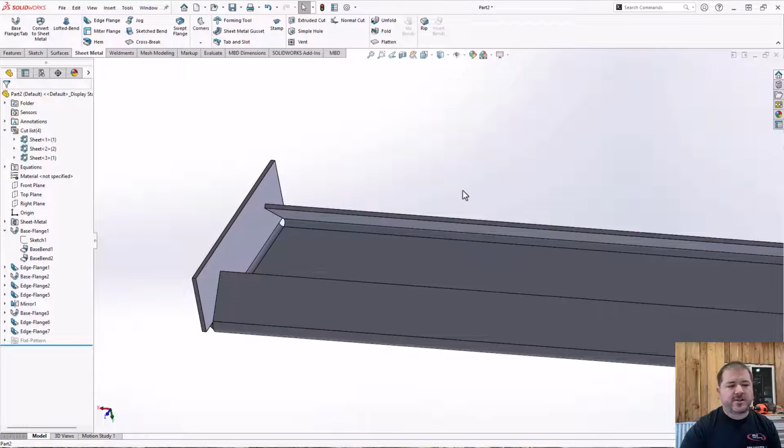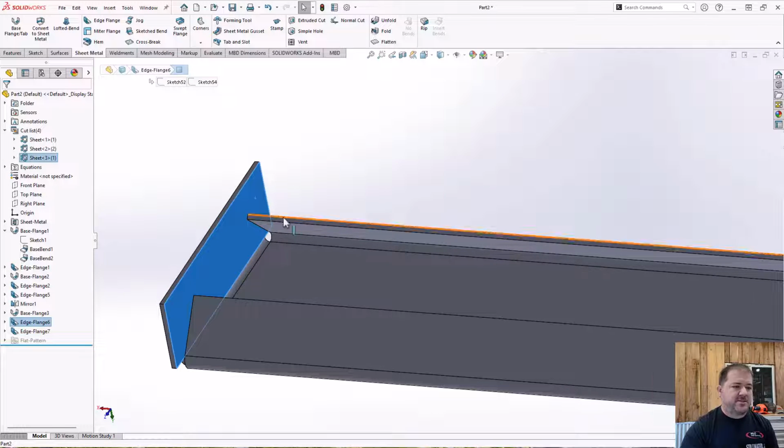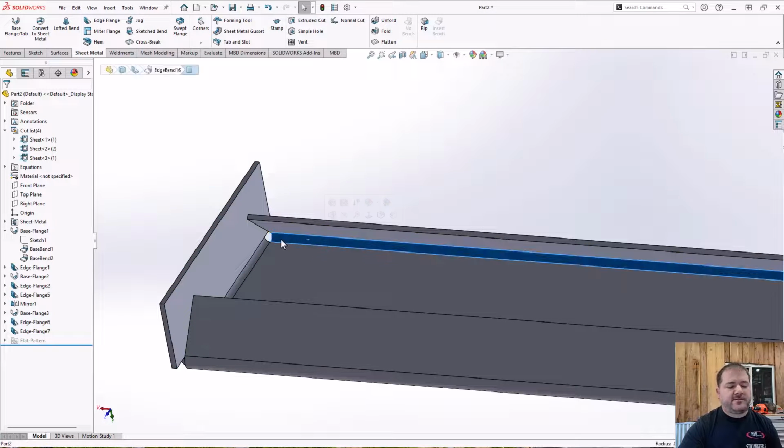For this one in production, I probably would take the option where I add some relief cuts to chamfer these edges so that the bottom die doesn't interfere. So I can have a continuous bottom die, a shortened top die, right? That's the exact size or width of this. And a lot of times you'll see at the brake press, you'll see lots of long dies, and then you'll see various different sizes of short dies that can be used to make up any of these random sizes that you might need to do.